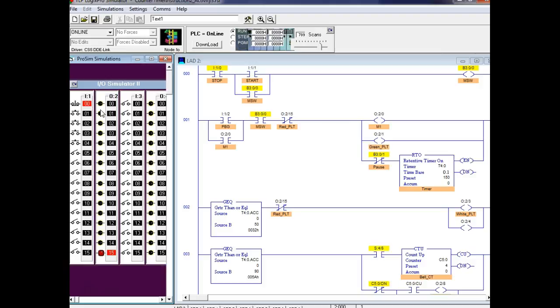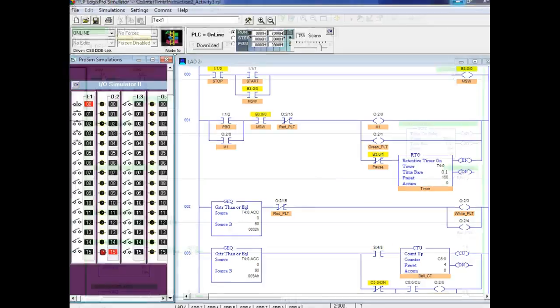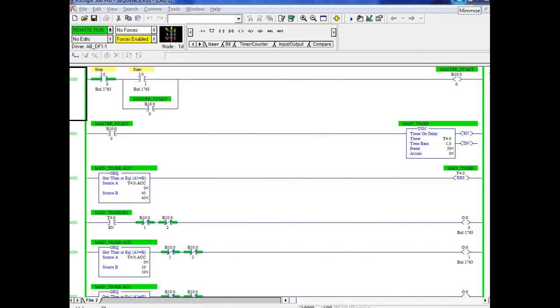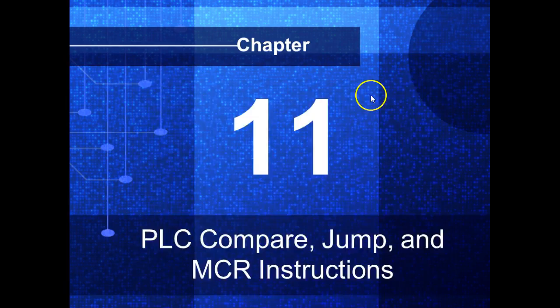A retentive timer, when we disable it, it does what? It maintains its count. But how do we get rid of that? Well, retentive timers, you have to reset it. So making it pause was interesting. And I realized, I was trying to see where you got that bit that you made pause. We'll come back and look at this after we get over these.